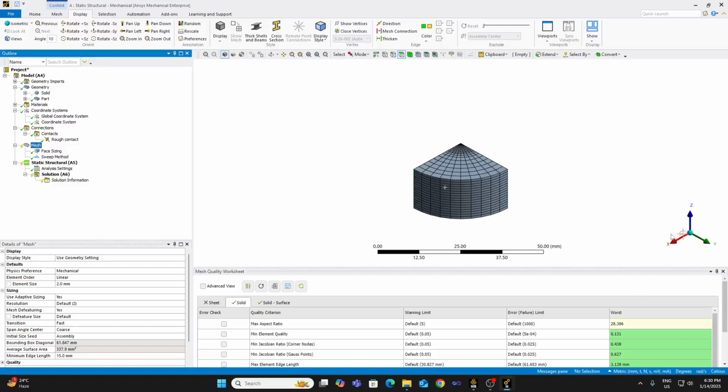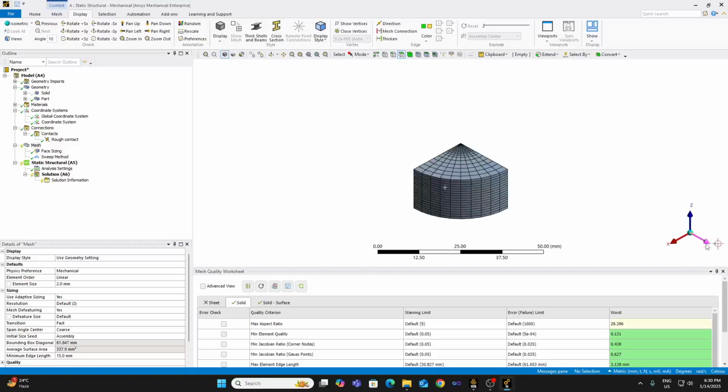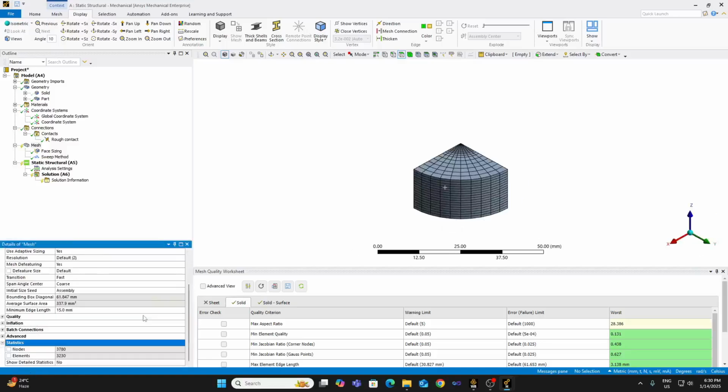Yeah, so it created the mesh. Mostly they are brick elements, so I'm fine with this. That's skewed. Skewed is not desired, but I would get arbitrary quadrilateral elements anyway, because in only one particular corner there is mesh refinement, so it is mostly okay, I guess. There are two reasons I'm going with lower order elements. Firstly, the higher order elements with quad type are serendipity elements, and there are reasons we would like to skip that one. And number two is the mesh count, because with lower order elements the mesh count is lower.